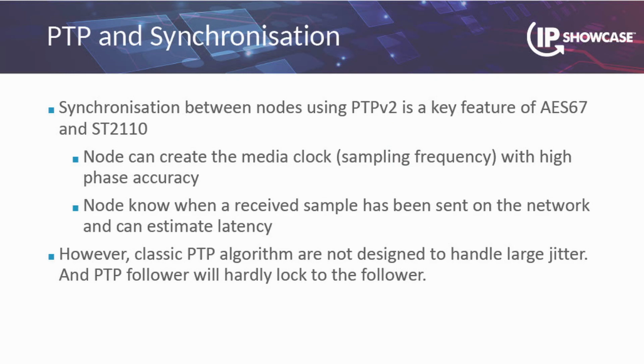Of course, then, when you acknowledge there are delays on the networks, you also need to do synchronization. And synchronization is not really impacted by the delay, because PTP will correct the delay easily. It is impacted by packet delay variation. The geographic delay is not a problem, but the packet delay variation is a problem, up to the point that some nodes cannot really synchronize on a highly jittered PTP signal. So you have to find solutions.